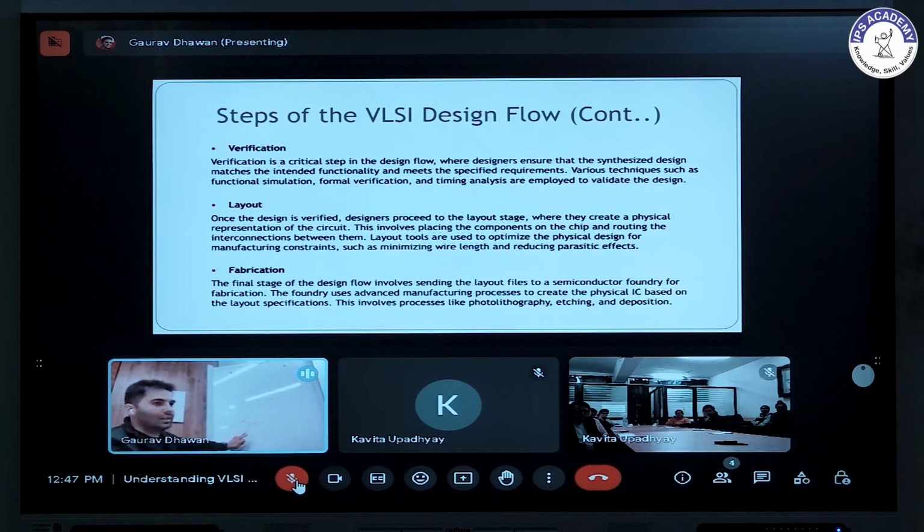So what they will do is take this and start drawing the circuit like this. That is my VDD, this is my VSS, this is my diffusion, this is my PMOS, this is my NMOS, right? This is my source, which is connected through a metal gate. This is my drain, connected through a metal gate. Now gates are connected through metal again. So this becomes my A pin, this becomes my Y pin.